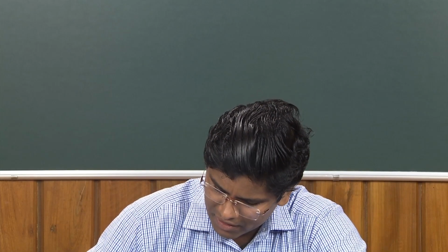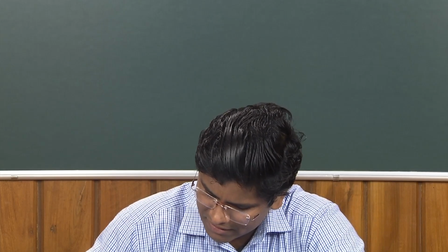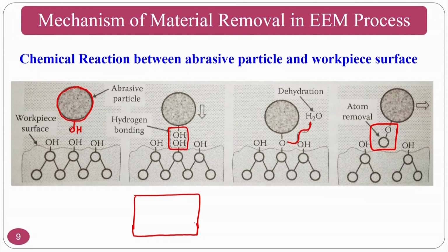Because of which, what are you going to get? If this is a surface in terms of grinding or diamond turning, your tool will go, again it will come back, your tool will go, again it will come back. So, this type of scratch marks will be there, even though you are going to get a surface roughness of about 20 Angstroms or something.